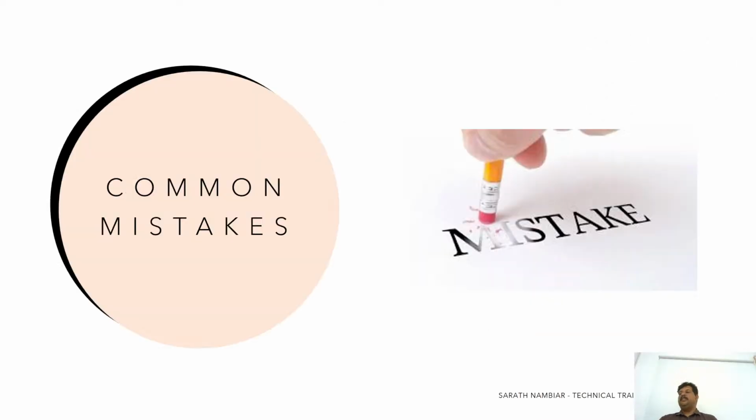Now let's talk about some mistakes. Learning tools is not enough. Avoiding mistakes is equally important. Common mistakes beginners make are: first, using the wrong tool for the operation; skipping the finishing tools; not following the proper sequence; applying too much force, breaking taps. The machine is not the problem maker most of the time. It is the tool selection that is the problem. So always think before using a tool.